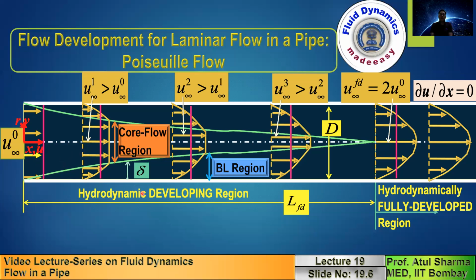The pressure of the fluid also drops due to the stickiness between the different layers of the fluid, and to maintain the no slip boundary condition, a velocity gradient sets in. So this velocity gradient tries to drag the pipe along the flow direction, so near the wall there is a shear stress which acts, whereas the pipe tries to resist that.